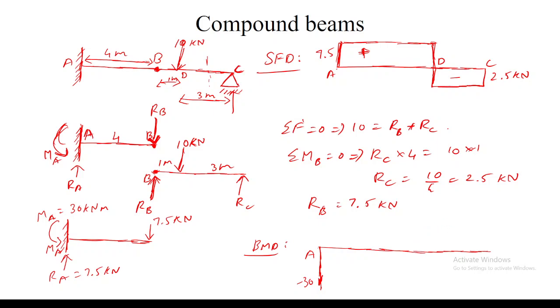Up to what point do I have to draw the straight line? Can you say what will be the bending moment at point B? Yes, at point B, the bending moment is 0. So we will draw at point B, which is exactly at its center. The bending moment is 0 because it is a hinge, so you won't be having any bending moment.